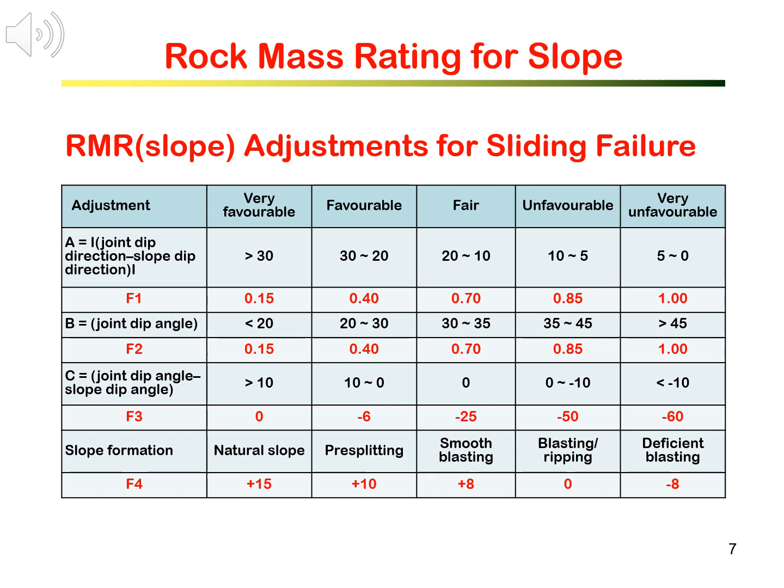Rho 3 is to calculate the joint dip angle minus the slope dip angle. If the joint dip angle is smaller than the slope dip angle, then we know the joint is daylighting on the slope. Therefore, a negative C value means joints are daylighting on the slope.